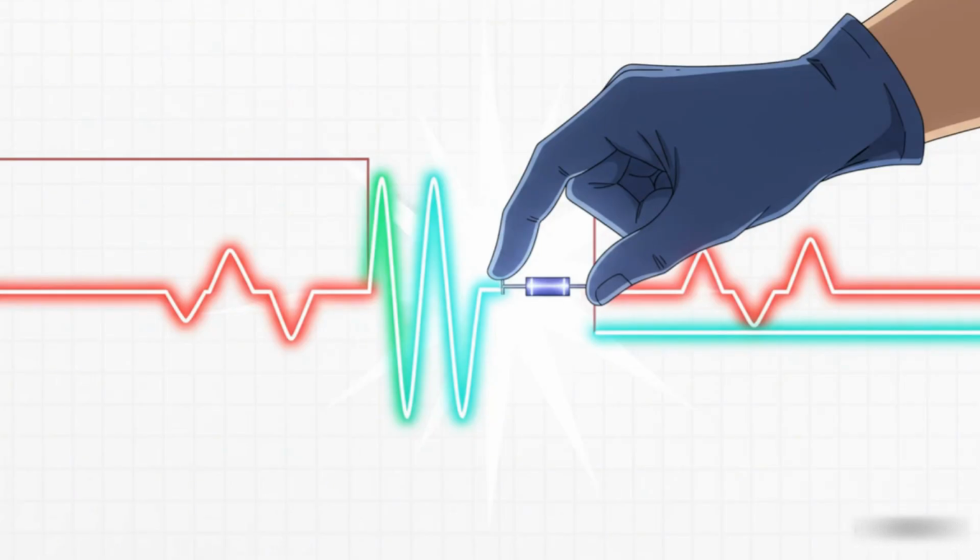And this is the part I love about engineering. Often these real-world headaches have these beautifully simple, clever solutions. For this bias current problem, it turns out that by adding just one more carefully chosen resistor, you can make the errors created by the two inputs almost perfectly cancel each other out. It's just an elegant, simple fix.